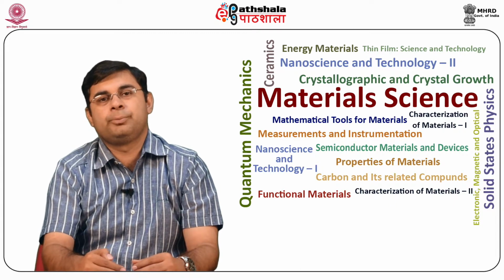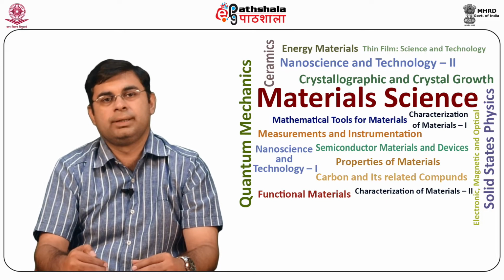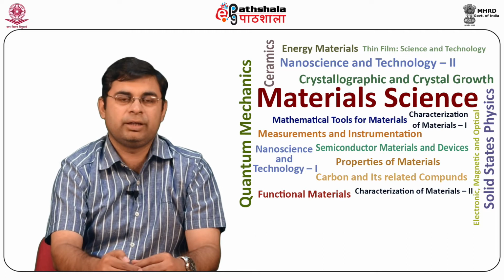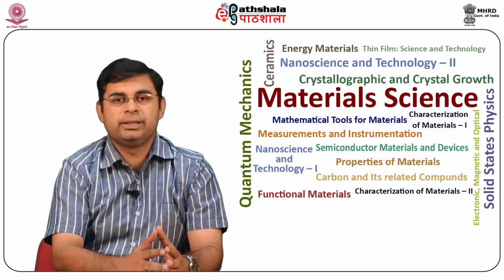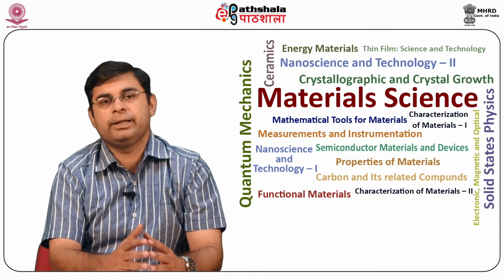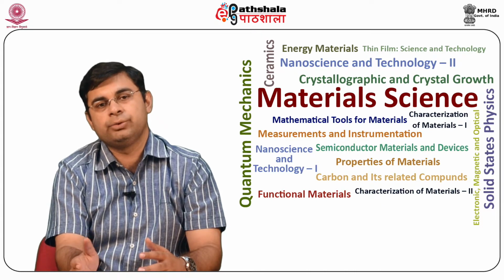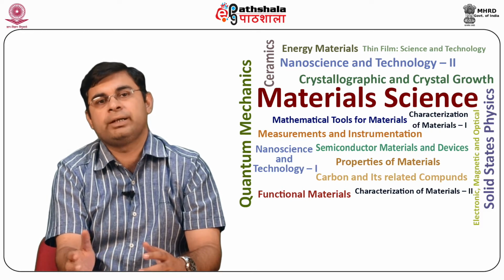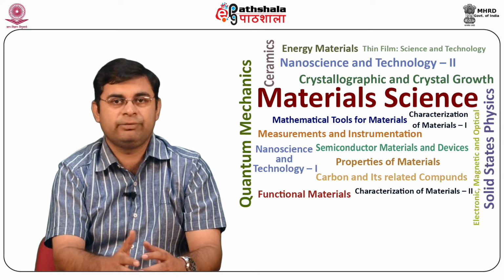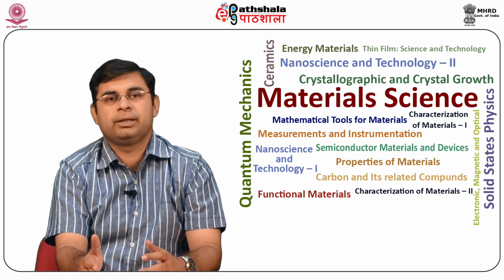Transducer operation via production of eddy current. Eddy currents are also called Foucault currents. They are loops of electrical current induced within conductors in the presence of a changing magnetic field. In such a transducer, a conducting plate is kept near the coil carrying alternating current, and eddy current is induced in the conducting plate. This plate produces its own magnetic field in opposition to the magnetic field created by the coil. Thus, the currents induced in the plate reduce the net flux associated with the coil.